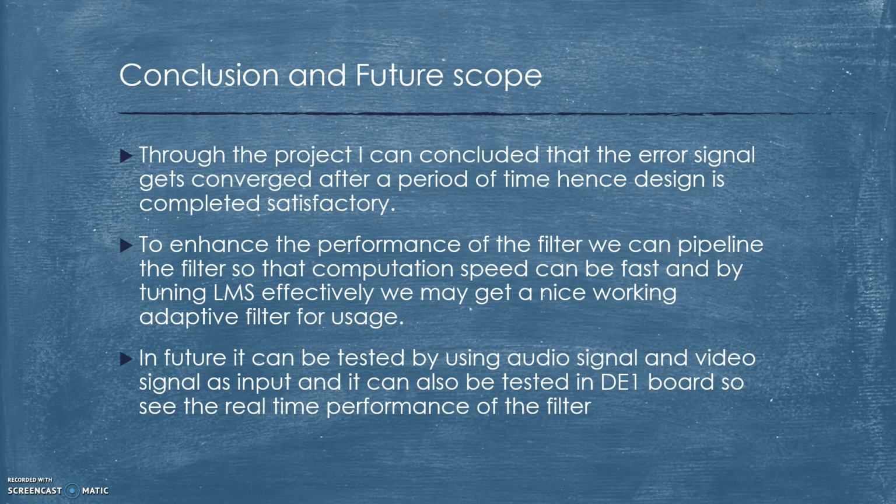For the future, there is a lot we can modify and we can enhance the performance by pipelining it more, like we can pipeline the filter to increase the computation speed so that it can be fast, and we can tune LMS effectively with a little bit of modification so that it can give correct coefficients and values for the calculation.